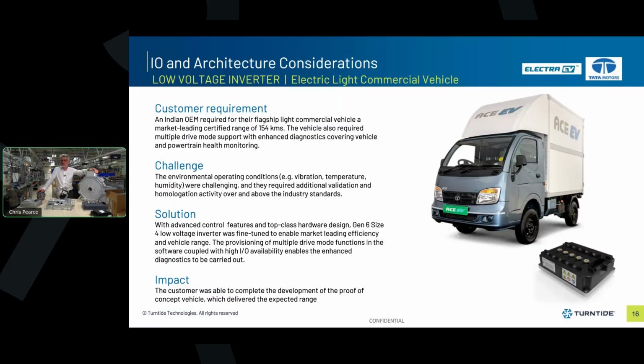We were integrating the Gen 6 platform into this vehicle, into an application space which requires specific and bespoke CAN interface with unique controls, as well as some of the controls we've already specified in terms of dual channel throttle, foot brakes, and direction switches,